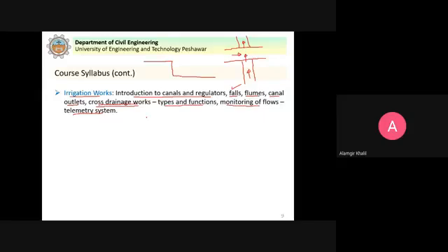So you just need to measure the depth of water, and you can use the different gauges, manual or automatic, and then you can use the rating curve to estimate the discharge at that cross section. For that, we can also have telemetry systems, automatic systems. So the depth is recorded and then it is transmitted to the control room where the data is processed and stored.